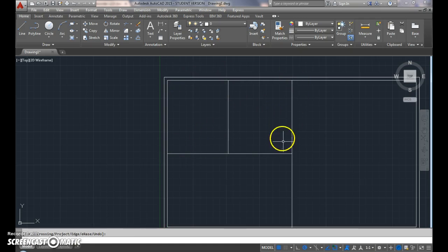The difference between interior walls and exterior walls is the wall thickness. These walls are all based on a 4-inch wall thickness as opposed to the 6-inch. Again, a 3.5-inch stud, and you have a 1/2-inch drywall on either side. Now, if you add those up, you're saying, well, that's 4.5 inches, and that's true, but the 4-inch wall thickness is enough to give us our defined space.